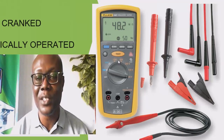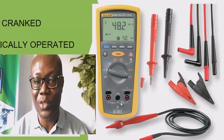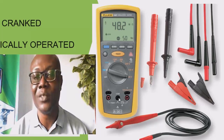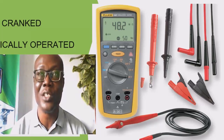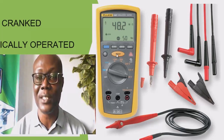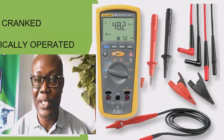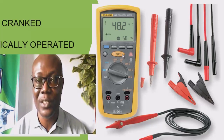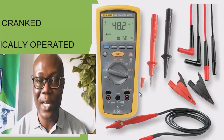So when you do the appropriate connection, one probe here, the red probe here, then the black probe here, and then you connect them to the equipment or wherever you want to test, or the component that you are testing, then you press the injection, that is the test button. When you press the test button, it will do your IR test for you.